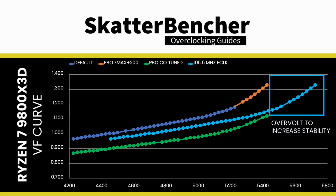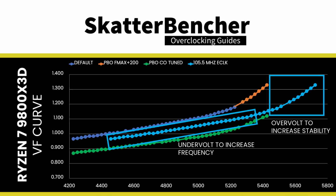We want to use Curve Shaper for 2 reasons. 1, we want to use positive values to improve stability at the upper end of the curve, and 2, we want to claw back the undervolting potential at the lower end of the voltage-frequency curve. For the first objective, we can use positive Curve Shaper values for high and maximum frequency regions. For the second objective, we can use negative Curve Shaper values for min, low, and medium frequency regions.